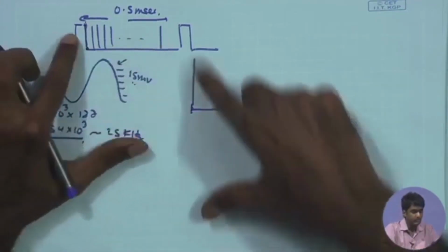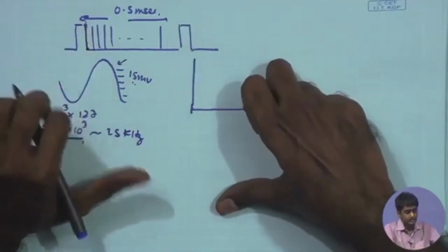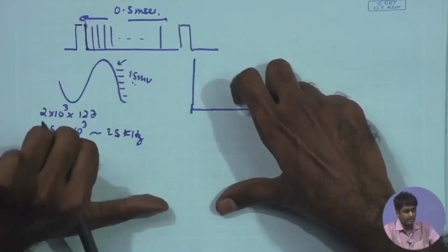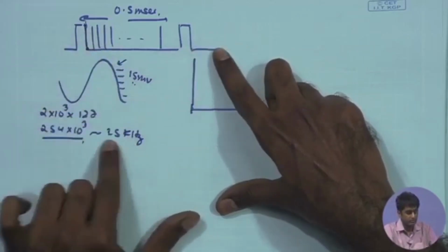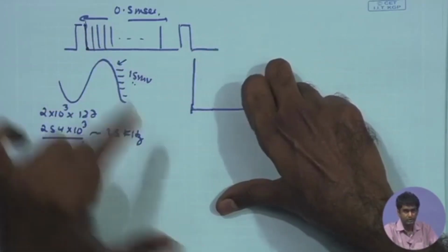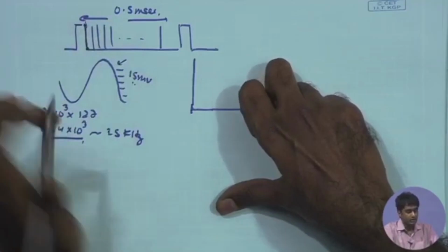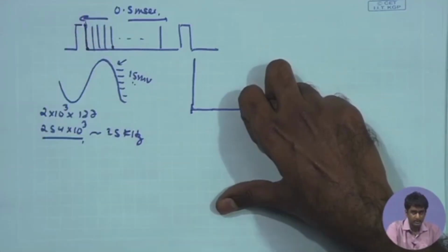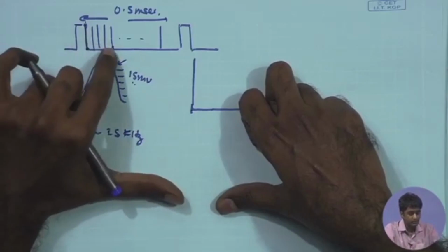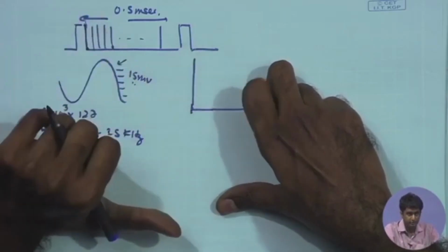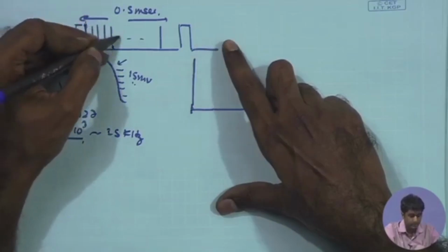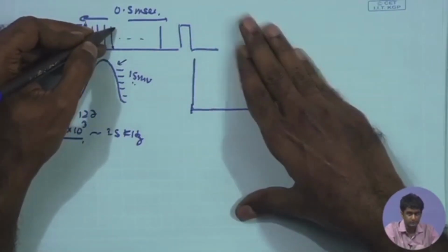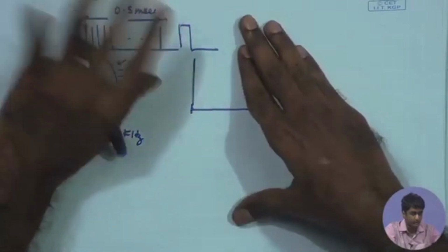And now, if I look at the comparator bandwidth and the gain required to satisfy this 25 kilohertz bandwidth for the clock. So, one important factor would be the speed of the comparator, how fast the comparator should operate, and for that we need to look at the behavior of the comparator between the clock pulses at which it is having a transition.